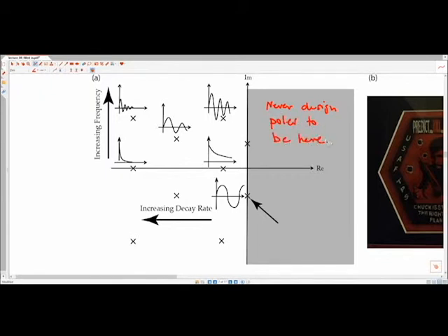And then in general, if we have poles that are really close to the imaginary axis or on the imaginary axis, the system will oscillate forever. There are a few examples of where this is desirable. You can think of systems that you want to oscillate, like there are a lot of things in electronics where you want to design oscillators. In general, this is very unfavorable. So oftentimes, designing poles to be on the imaginary axis is a bad idea as well.